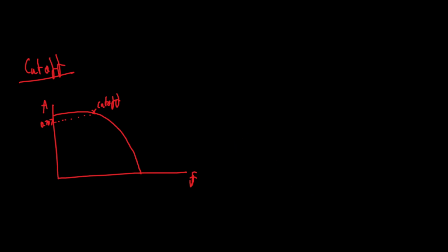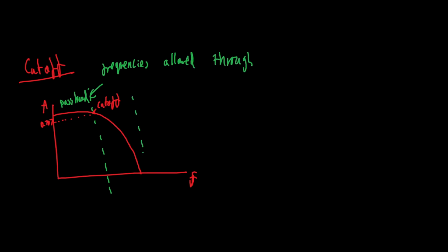And there are some more important things to look at with this. There are actually 3 parts of this low pass filter. There's your pass band, and these are the frequencies that are allowed through. Then you have your stop band over here, which are frequencies that are blocked.